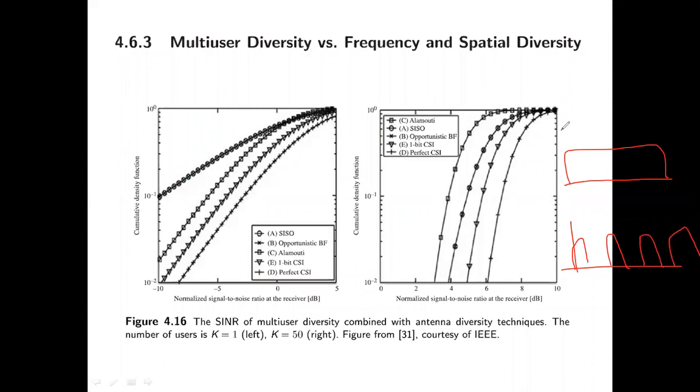So in place of a very large data that you are going to transmit, suppose your channel was suffering deep fades in particular places, say maybe here. Where you have split the entire data across the entire frequency band in randomized locations, the data was not all in this particular faded band but was spread, so you can employ very high speed communication with fewer losses, and you achieve frequency diversity.